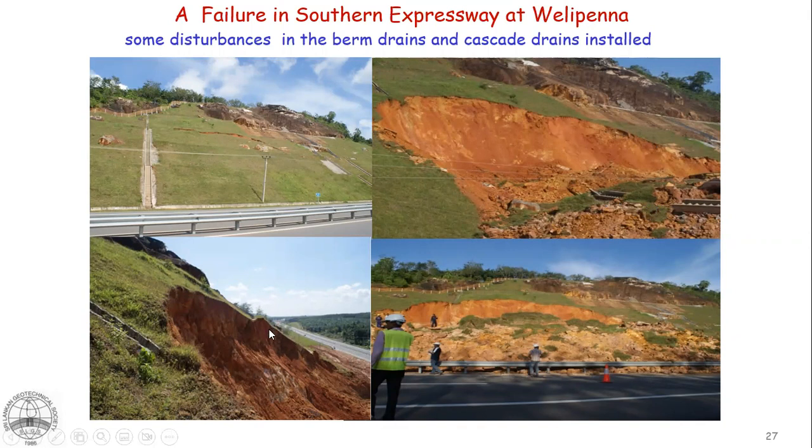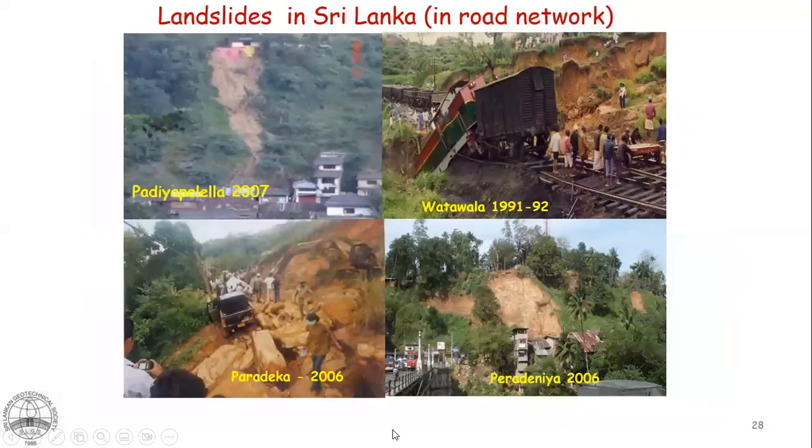You can see here that the depth of the failure surface is quite shallow, right? The whitish clay soils were here. So this was where the initial destruction happened, right? It flowed down as debris covering 2 lanes of the expressway. This happened after a few days of heavy rain, right? But the groundwater table has not risen. The matric suction is completely lost over here.